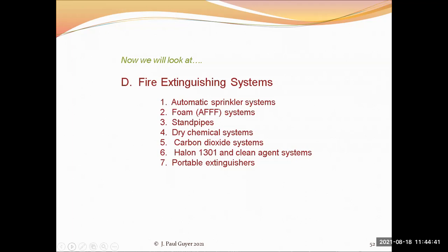The standpipe, again, that's typically the vertical pipe running up the stairwells, and that is pressurized. On each floor of a multi-story building, there is a connection where the firefighters connect to that, and they then have pressurized water to fight the fire with. Dry chemical systems, again, are typically used where water is not effective.